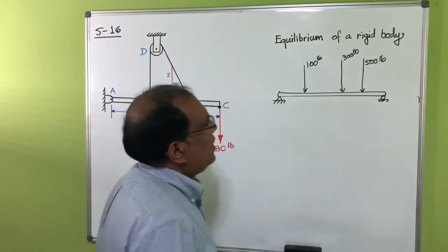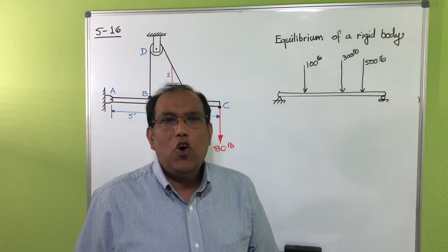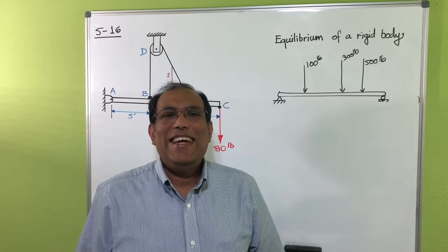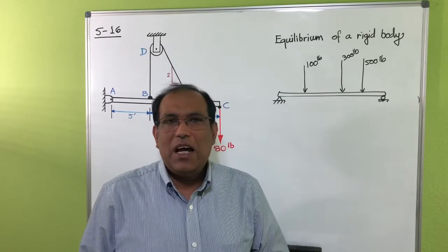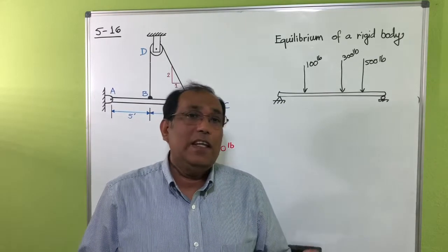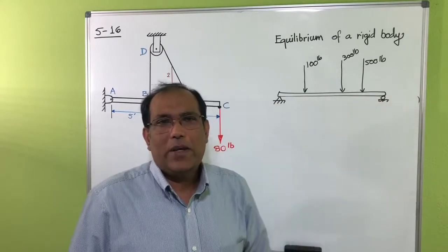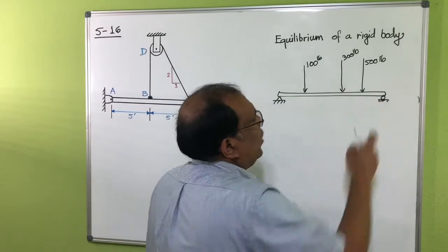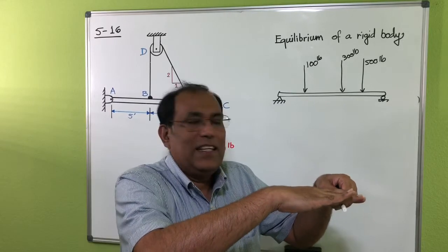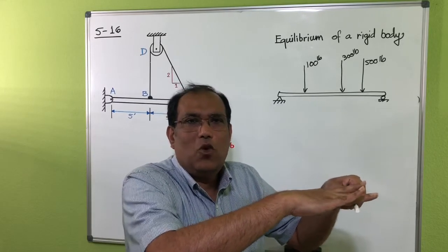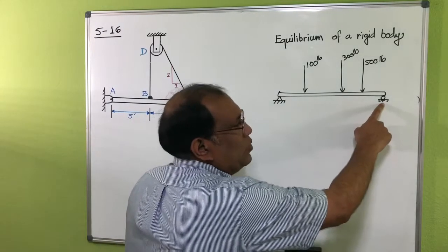Now you can see here, let's say this is a steel member, and the steel member will change its length because of the temperature variation. In summertime, you can understand the temperature will be very high. At that time, this one will try to elongate this way. That's why we usually put a roller here, so that if the length increases, this one can increase a little bit there too, because the roller can roll. So there is a reason why we are using this one.